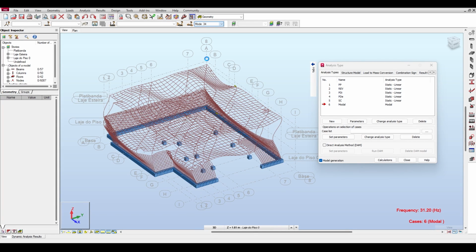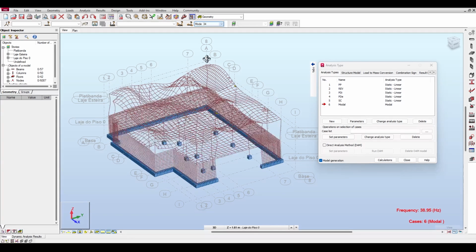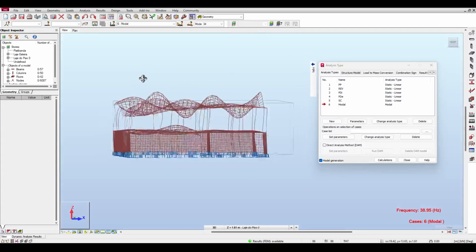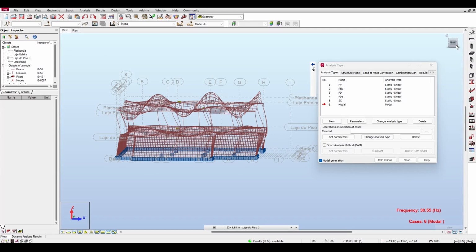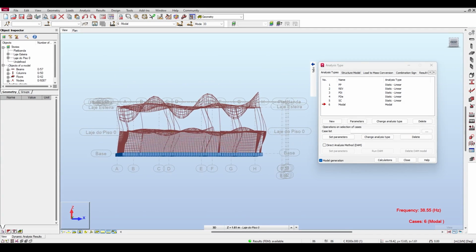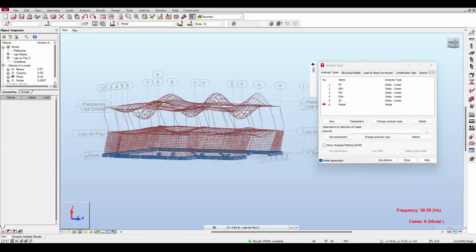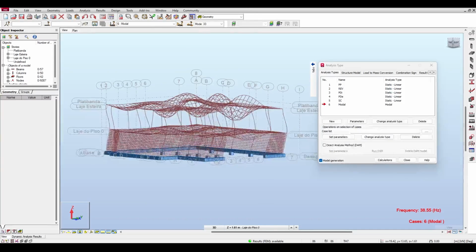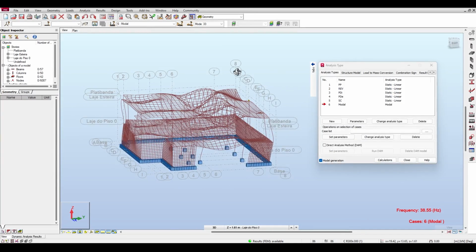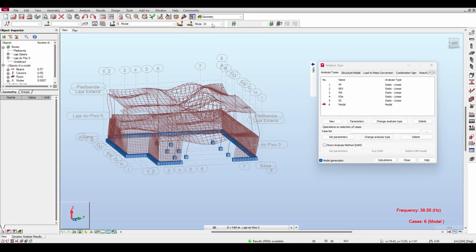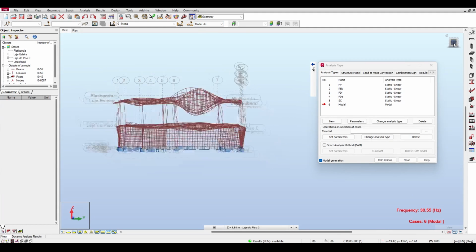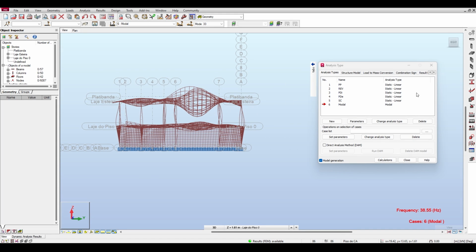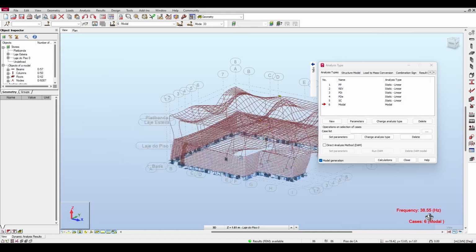Look at this. This is in the ballpark of the 40s, I think. Let me check. Yeah, we are now in 40 Hertz. Now, it becomes harder and harder to move structures like this. What I'm saying here is, you just cannot simply force a certain mass participation because sometimes the mass just doesn't participate. It doesn't participate because for all means and purposes, going to the 33rd mode at 40 Hertz is interesting, yes, but is there really a force that can excite the structure in that frequency?